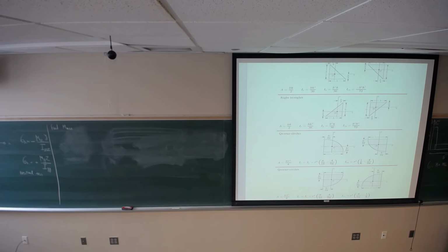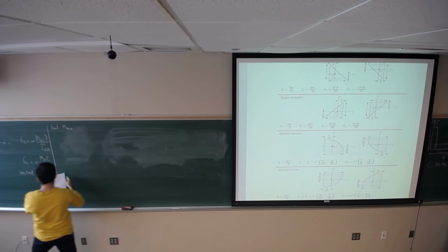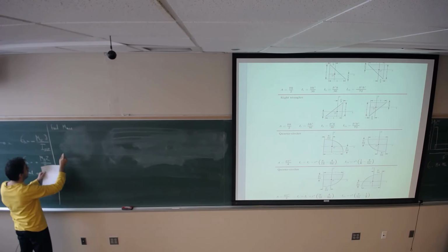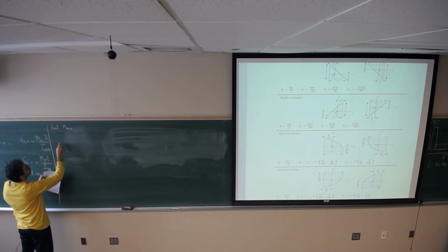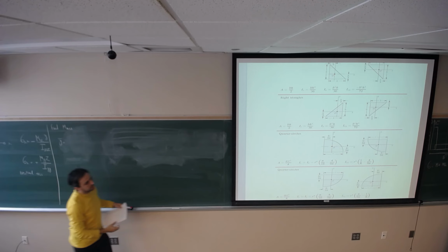So I know it's going to be at the middle. The only thing that I need to find is how far I should go up to draw the neutral axis in X direction. So I'm looking for Y bar.